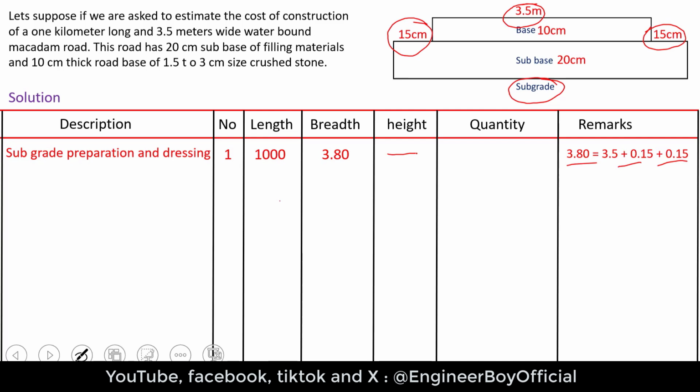So we will just multiply these three columns in order to have the quantity of the subgrade. And this should be actually 3,800 square meters. This is very simple and straightforward. Next, as you can see, we have the subbase, which is, you can say, the second component, just laid above the subgrade, okay?